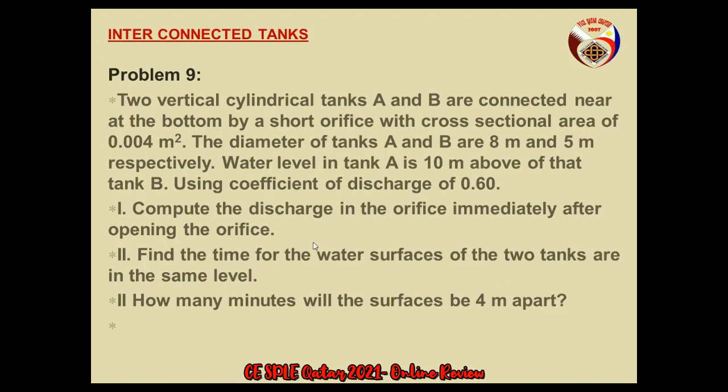So immediate. What does immediate mean? It's not a falling head. Immediately, so it's just simply Q equals C times the area of the orifice times the square root of 2gH. That's all there is to it. Then the time for the water surfaces to be at the same level. How many minutes will the surfaces be 4 meters apart? So number 1 is just simple